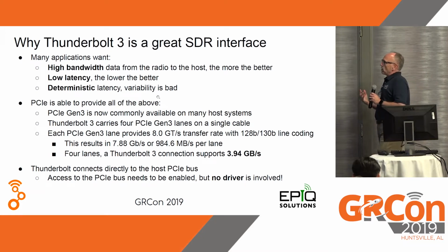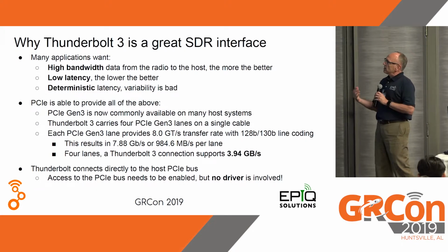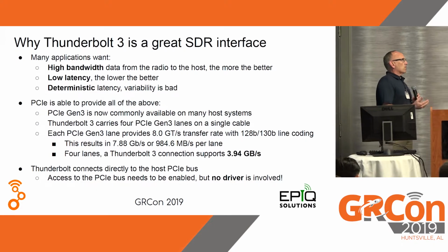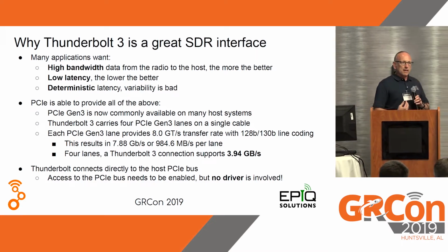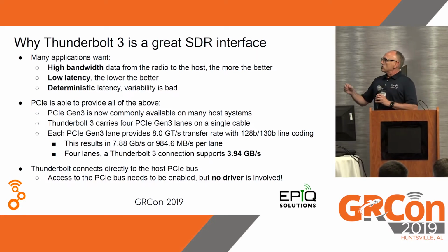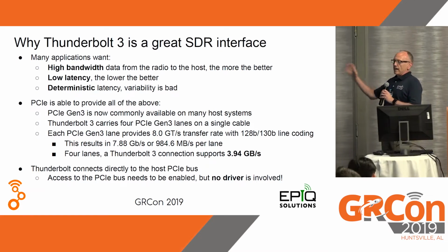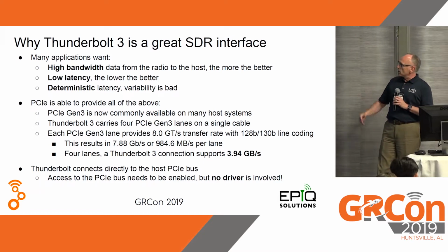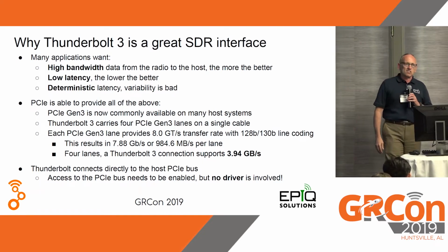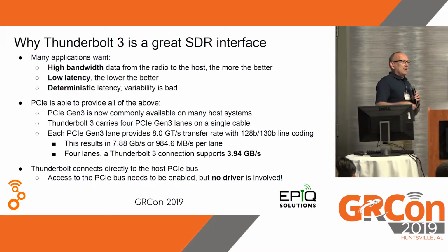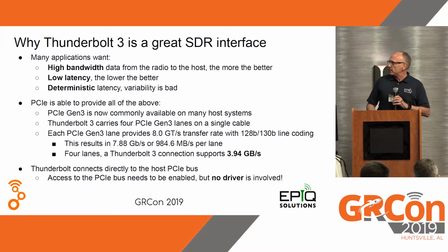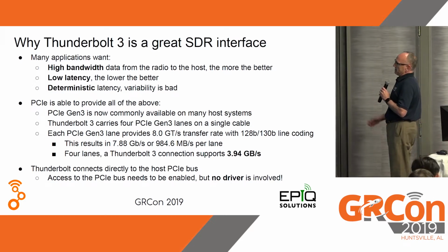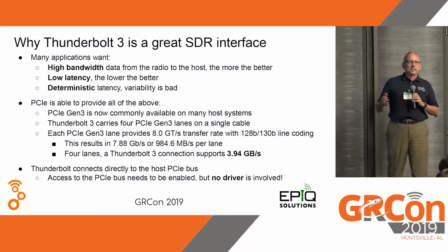Why do we want this? Why are we so excited about this? Well, with SDR technology where it is and where it's going, we're always getting to higher bandwidths and higher channel counts. If you have high bandwidth, you can always go lower, but the higher the better. We want low latency, and we want very deterministic paths, so deterministic latency on all of our lanes. PCIe is really good at that.